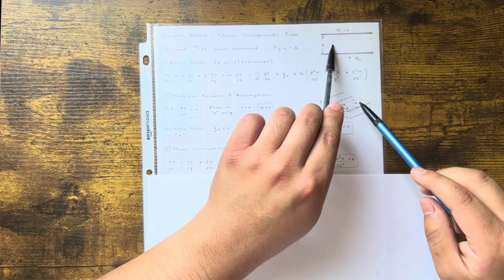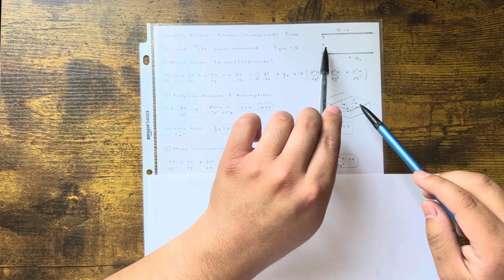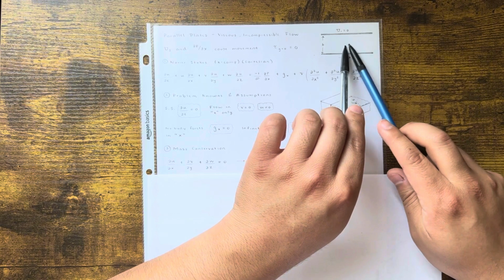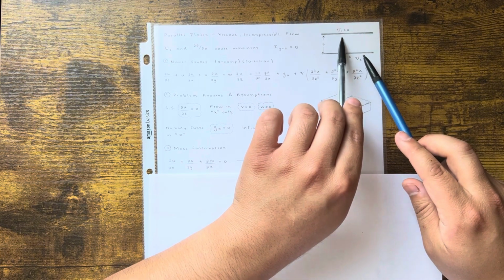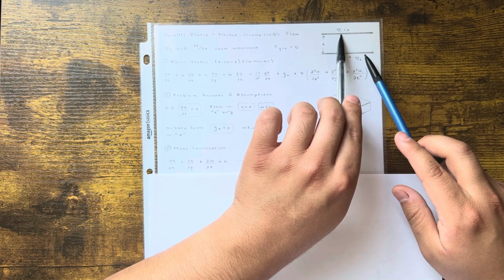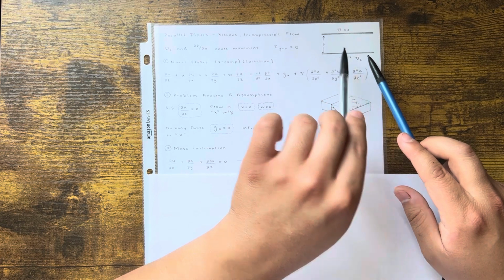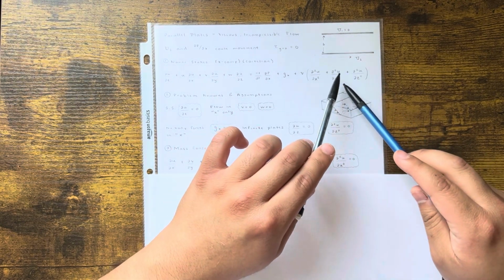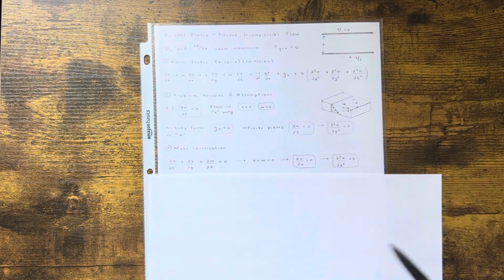And we know this exists because of the velocity of x with respect to y. At the very center, at b over 2, in this case the height is b, it could be a very large magnitude of velocity. Imagine a big arrow. And then as you go towards the walls, this one's fixed, so you can imagine velocity is going to be 0. So you see velocity changes. It could go up or down along the height. And that's what that term is saying: how does velocity in the x change with respect to y? And that's what we're looking for.